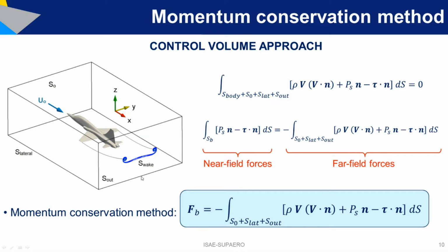What you would like to do in a wind tunnel testing environment is that instead of measuring parameters on all the surfaces of the control volume, you would like at least to measure parameters at the survey plane, and ideally just across the wake. We will see that later on. We will just do in the next section a small improvement.